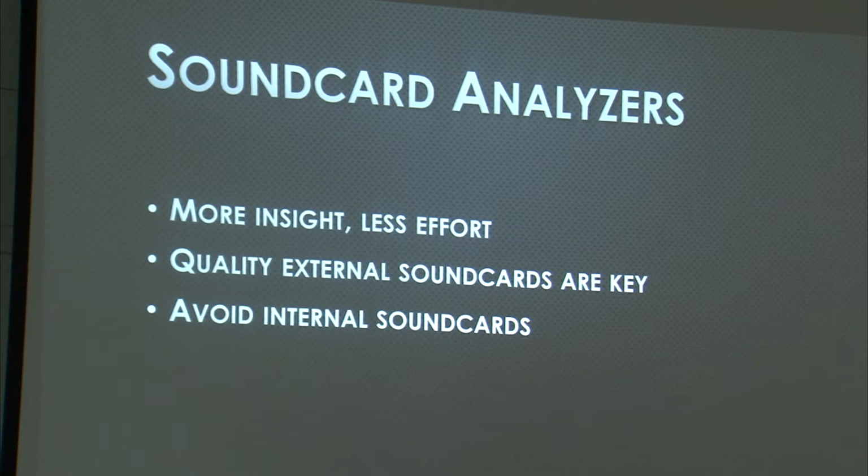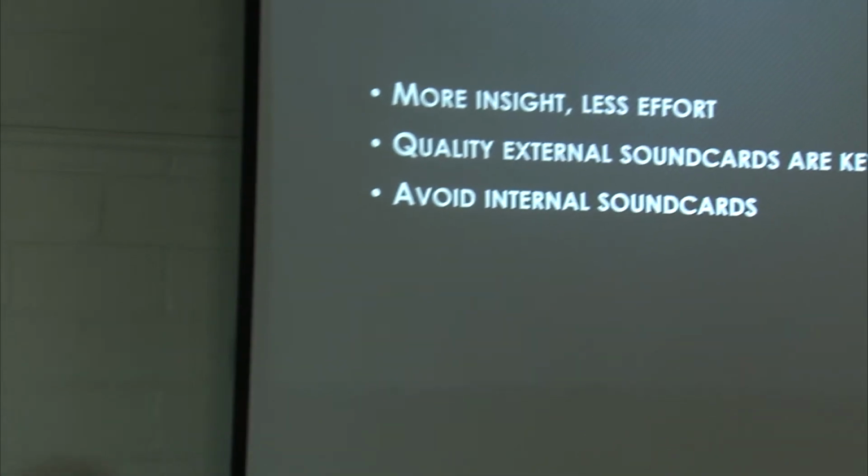And typical internal sound cards have variations on that. External sound cards work a lot better if they're selected right. So internal sound cards, again, work all the time as rule number one. There are some that are good. There was a short period there where the competition said we had to have a good sound card. That meant capabilities up to 192, 16-bit worth of actual accuracy, pretty decent signal to noise ratio, stereo line level inputs. That's important. At one point, the industry just sort of instantly morphed. So now they all look just like the headphone jack on your cell phone. They have one analog microphone level in that's very compromised and a stereo output, usually not terribly good.